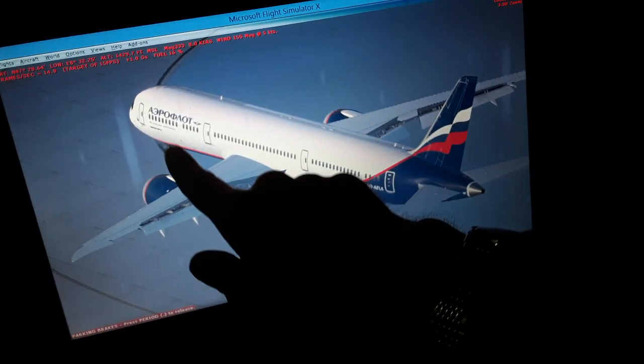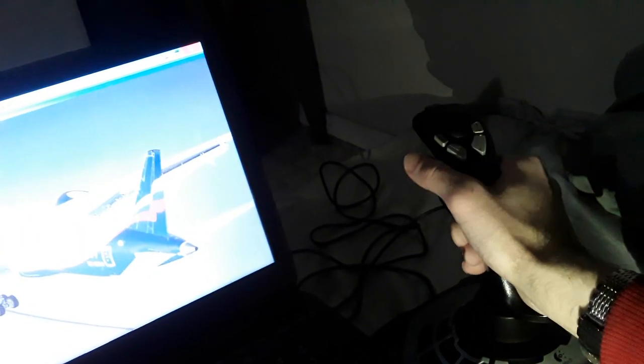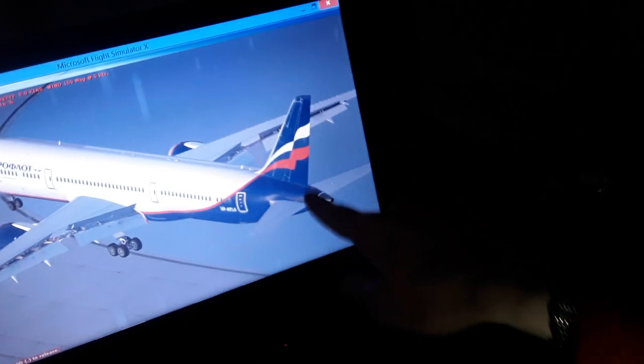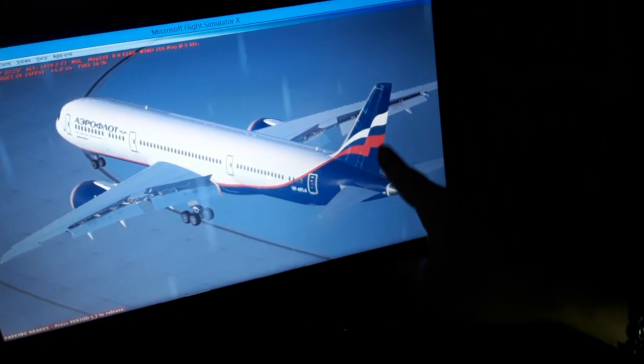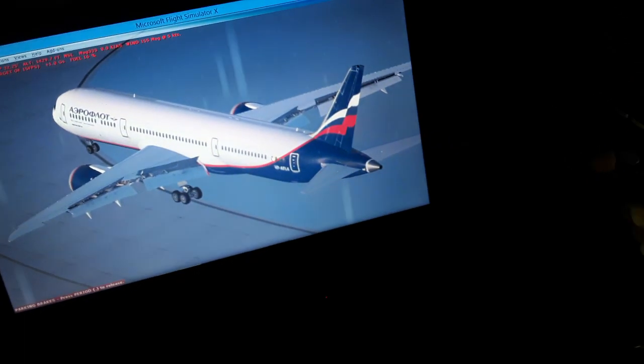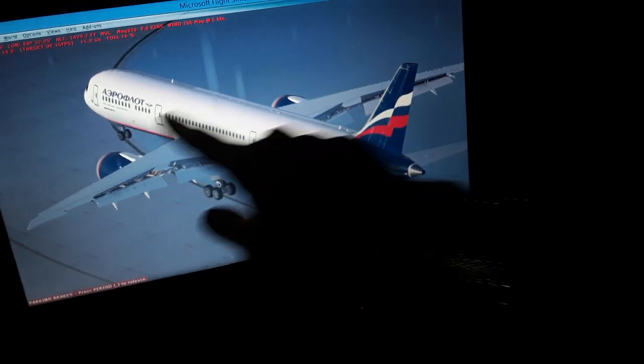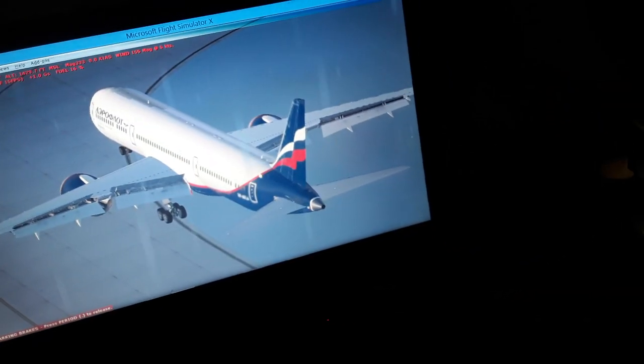It disconnects, so we have zero deflection from the front wheel above 70 or 80 knots. And we have only the rudder aerodynamically effective, so the rudder is also aerodynamically effective from 45 knots and over airspeed in takeoff or in landing, which gives a decrease in the deflection of the nose wheel.